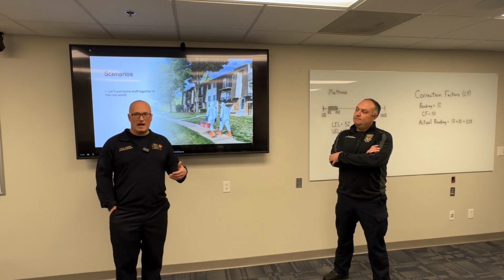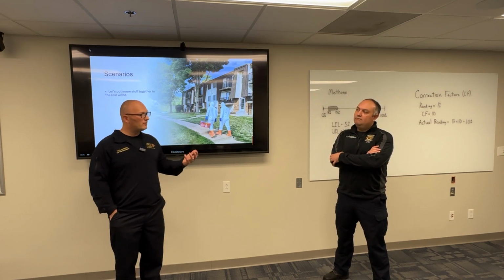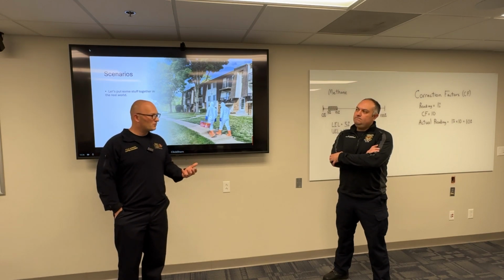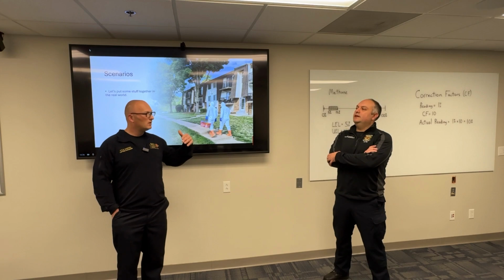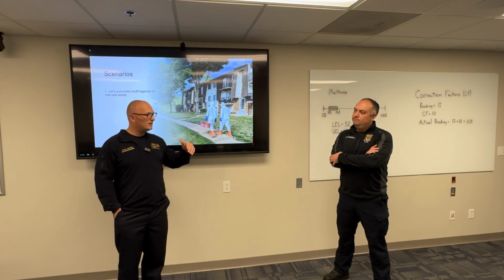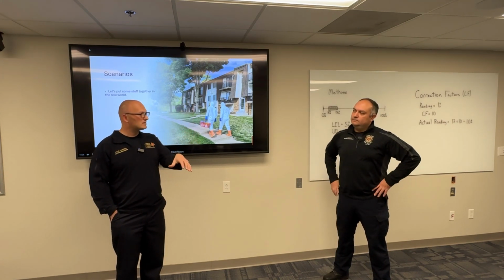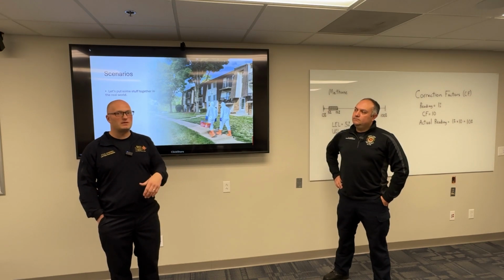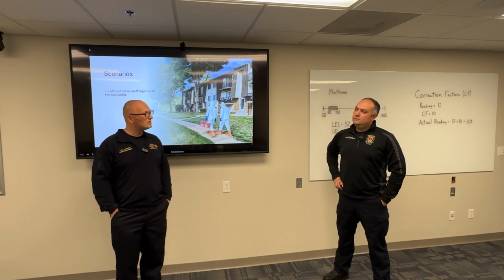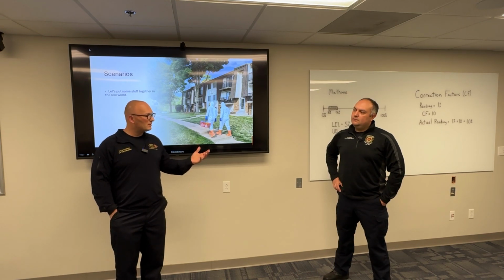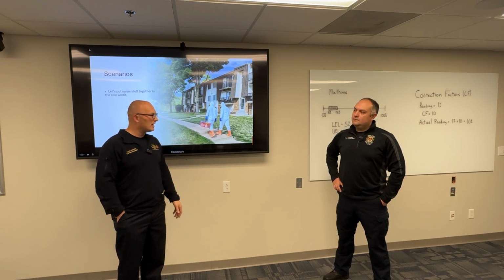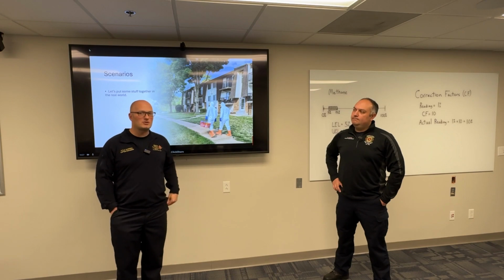The deeper we got into there, the higher the VOC readings, and it's really just playing detective, trying to figure out why we are getting these readings. Obviously it's going through the house because it's going through the HVAC system. We shut that off, ventilated, and tracked it down to this room in the finished basement, and then tried to figure out what it was and where it was coming from. At one point MSD was involved because they were thinking there might be something in the drains. So we were really just going in and trying to figure this thing out.